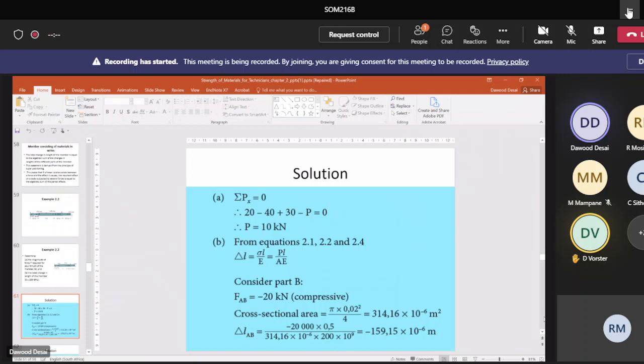Now we finish the first equation. Remember I said choose one equation, expand it, get a ratio, and then go back to your second equation. The second equation is the total change in length formula. So you take your ratio equations and you substitute them in there. Here it is done. You only have one unknown, you only have BC, so you work that out. The stress in BC is 43.752. Then you substitute this stress into equation 1. You get the stress for CD and so forth.